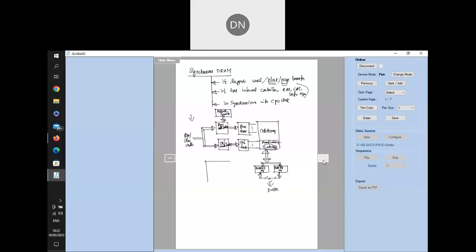One speciality of this one, as I said, is that a controller is built into the synchronous RAM. This controller has what is called a mode register, where I can select different modes of operation: word transfer, block transfer, page transfer, and configure it like that. It is also capable of generating all the timing signals like RAS and CAS.